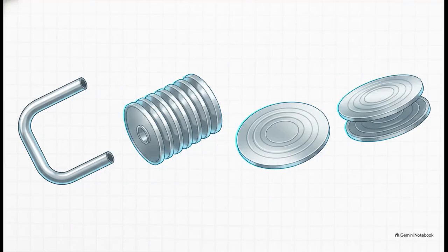Well, industry relies heavily on Bourdon tubes. These are curved metal tubes that literally try to straighten themselves out as pressure increases inside them. A standard C-type tube, which is bent at 270 degrees, handles lower ranges up to 60 bar. But spiral or helical tubes, they have way more windings, so they can handle massive ranges, literally up to 7,000 bar. Then we have bellows.